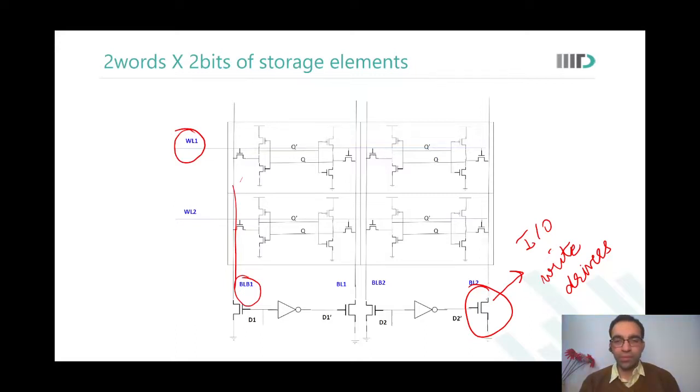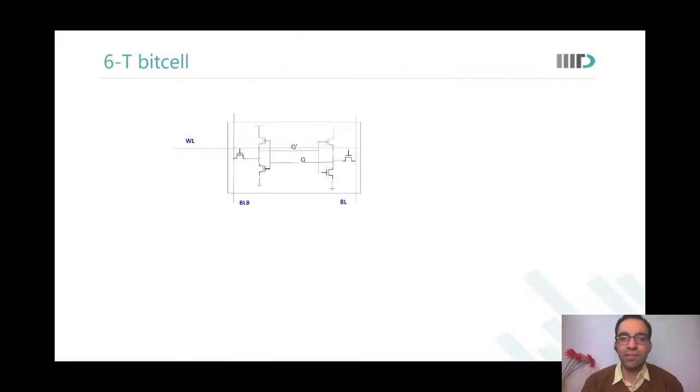So with this, now we say that my one memory cell has only 6 transistors, where there is bit line, bit line bar, and word line. They are the 3 interfaces. Some things that go out and in. They carry information in and out of the memory cell. They control the memory cell. And then inside the memory cell, you have the Q pin and the Q bar pin.